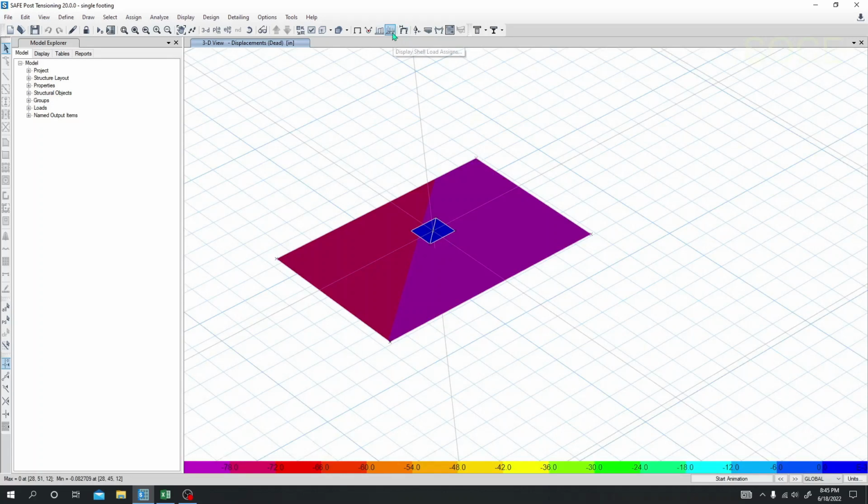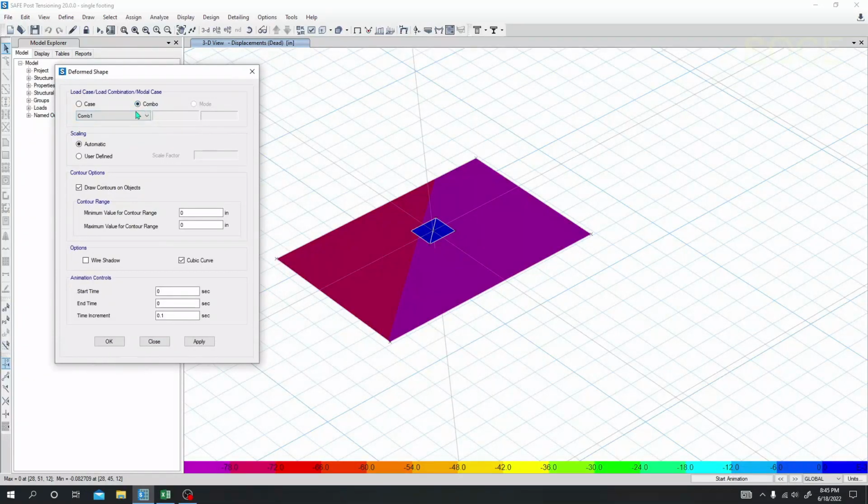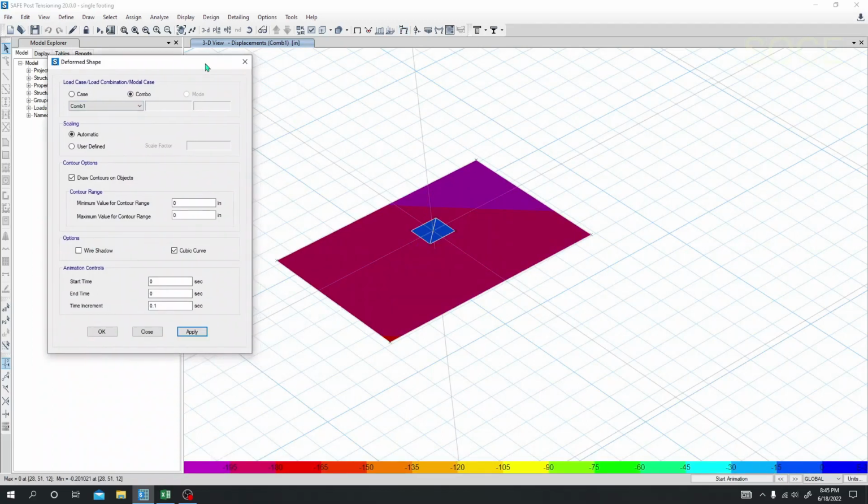So for that, here, deformation from combo 1, and just simply click here. Okay, so here what is the displacement? We have to take our displacement from here. So just see, our available settlement is 0.9, so on 1 inch, but here this is very low. So if we see here, this is 0.2. So we have the opportunity to decrease our slab size and thickness also.